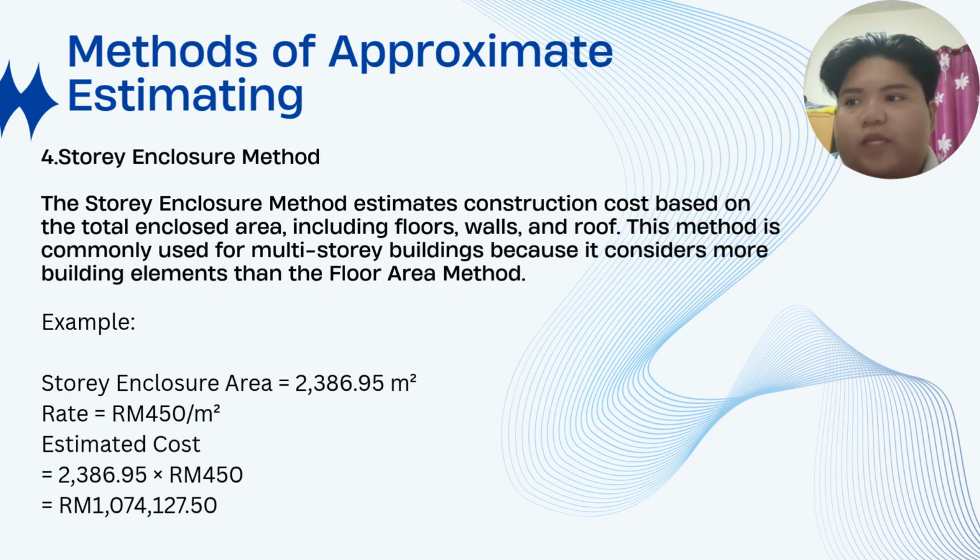Story enclosure method. The story enclosure method estimates construction cost based on the total enclosed area, including floor, wall, and roof. This method is commonly used for multi-story buildings because it considers more building elements than the floor area method.